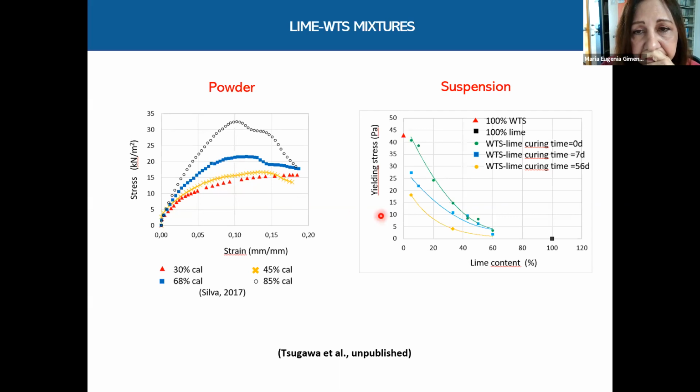But in the second case, surprisingly, shear strength decreases with lime addition and with curing time. This suggests that those chemical reactions associated with lime stabilization just occur below a certain water content. And also that shear strength in the mixtures we studied at early ages must be just due to the addition